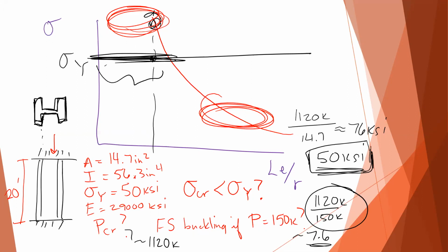All right. Okay, so with the last few minutes, I want to show you one more concept or example. When it comes to buckling, oftentimes the problems are going to be heaviest on the static side. The buckling is one equation that I've just given you, pi squared EI over effective length squared. So it's one equation that, as you can see, you can spend 2 minutes calculating. So in order to make the question meaningful, oftentimes it's the statics that creates the most difficulty.